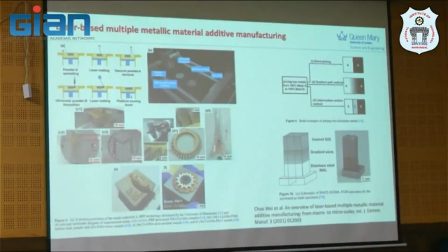So before we go further, we just want to have 1 or 2 slides about what we can do. If you remember, I mentioned functionally graded material. If you see this Eiffel Tower, it's actually copper at the base, and then this is steel at the top. In between, this is a graded structure, which is almost impossible in the traditional manufacturing process. Or you talk about multi-material, which is possible now in additive.